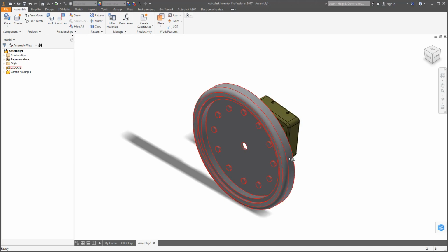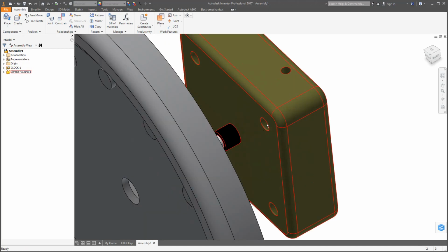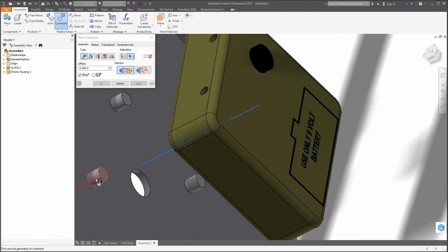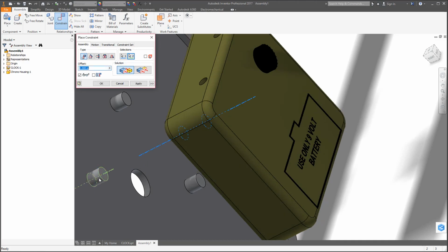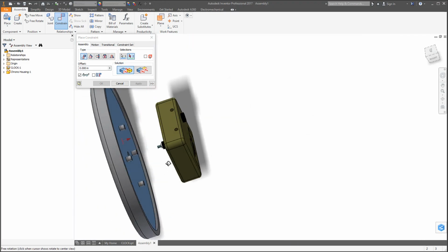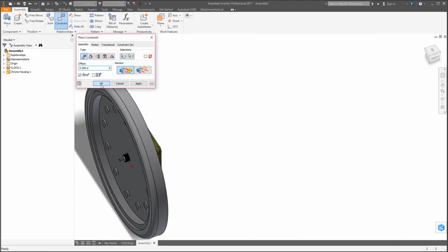because later on we have to attach the bracket to that with some bolts. Okay, now the next thing we're going to do is, let's zoom up there, and we need to go back to Constraint, select this hole. Now don't grab the green dot. The green dots are bad. You want the axis. Click, hold Shift and drag the middle mouse button, and select this axis here. Hit Apply. Finally, select this flat face on the back side of the clock, and then release and select this face here to lock it in. Hit OK.